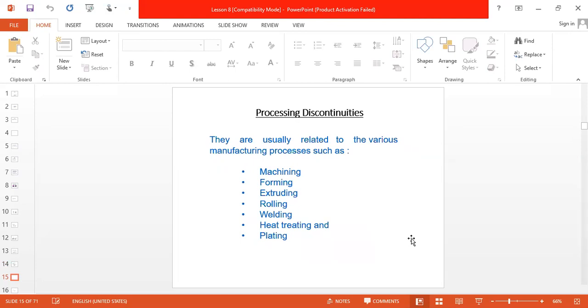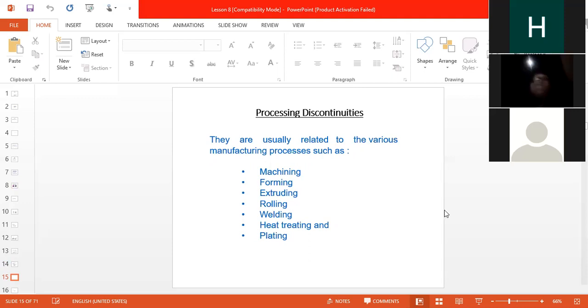You have to ask, because sometimes an indication comes when 50% of the material is carbon steel and the other 50% is a different material. That's why you also get indication at the junction of those two materials, because we know the permeability changes according to the material. Stainless steel permeability is different, ferrous carbon steel and low carbon steel permeability is different. Okay, so these are the things we have to ensure and correct.